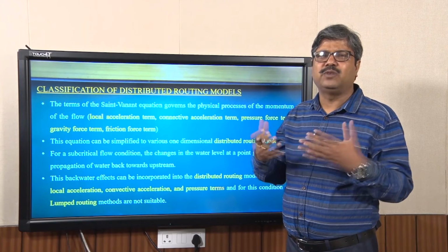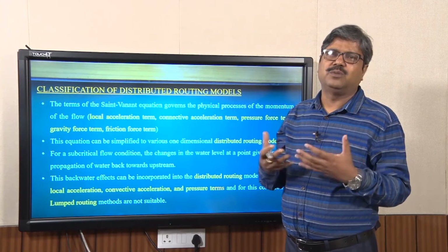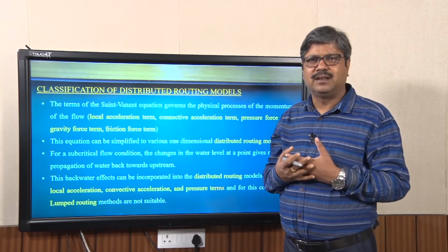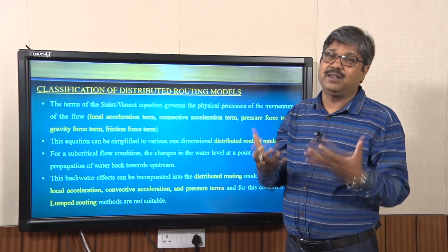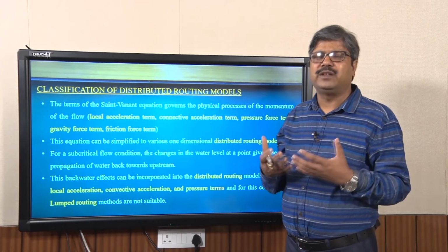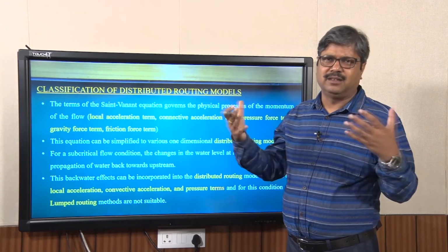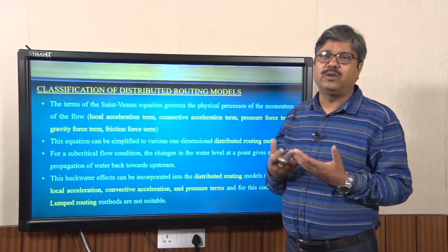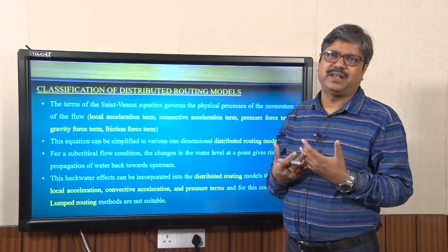That's the reason we need to give a lot of input data into river models even if you solve these Saint-Venant equations. Most places in the world also cannot get such detailed data along the rivers, like river depth and land use land cover, so we try to do simplifications.